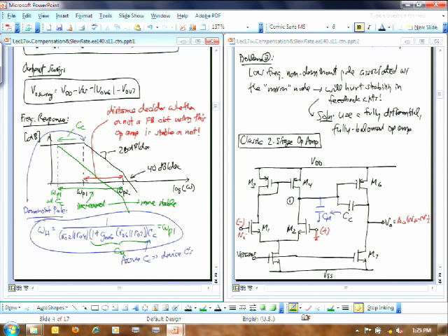Okay? The open loop op amp, you want the first pole and the second pole to be as far apart as possible in order to get the best stability. And so I'm not telling you how far apart. We're going to talk about that in several lectures after spring break. But right now I just want to give you that concept there. And why am I giving you that concept? I'm giving you that concept because you're going to need this concept when you look at your lab.